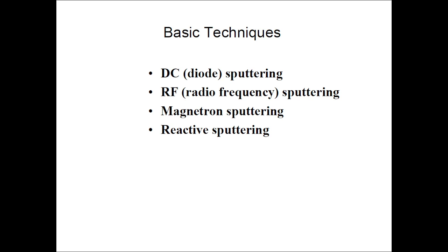So if you introduce a gas, sometimes this gas can actually oxidize the metal if we are using a metal target. So you cannot use that metal target next time for depositing metals, because it would have already oxidized. That we need to take into consideration. In sputtering itself, there are four kinds of sputtering, we can say, depending upon the source voltage that is used.